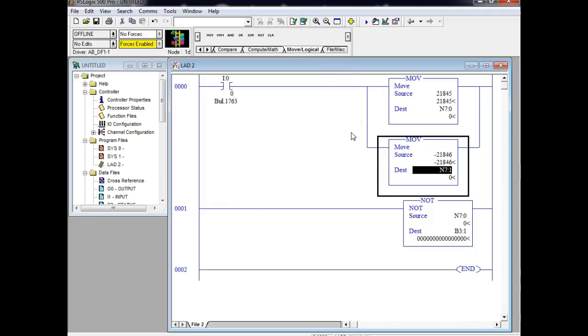The problem is your move instruction deals with numbers, base 10 numbers, decimal numbers. Okay, you understand that? So when I entered AAAA there, it didn't know what to do with AAAA, right? Because that is not a number. So what I did is I put an H after the AAAA. It gave me the actual decimal number that it represents.